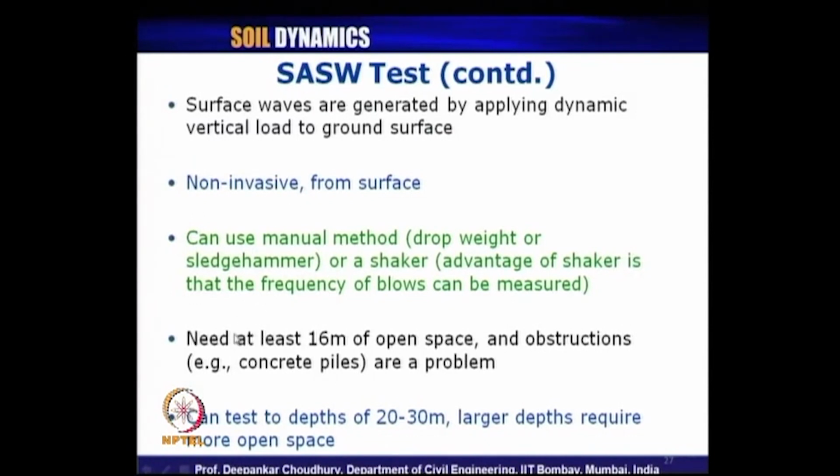What are the other major characteristics? For the SASW test, we need at least 16 meters of open space in the direction where the source to receiver is placed.